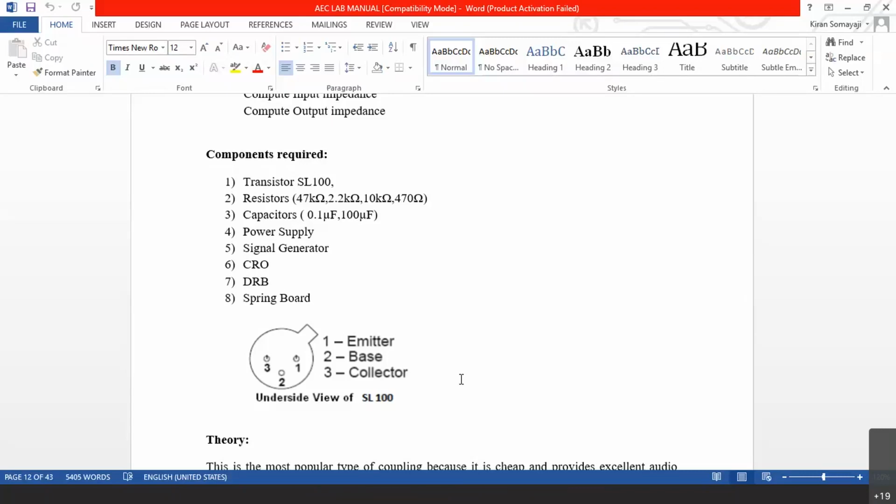The point is, in an amplifier, we are using the switch in half on, half off condition. So here, neither the voltage is zero, nor the current is zero. The switch is half on, half off. There is a voltage across the transistor that is VCC by 2, and a current through the transistor that is IC sat by 2. You are already familiar with these terminologies because you have studied this in the theory course. So VCC by 2 into IC sat by 2 is the power across the transistor now.